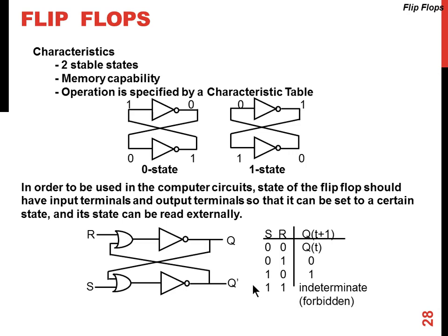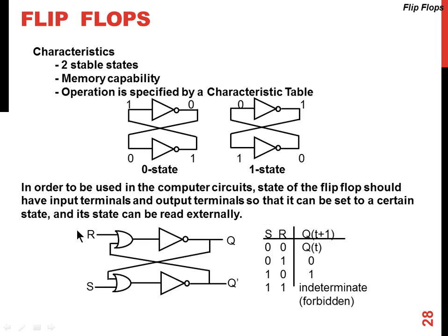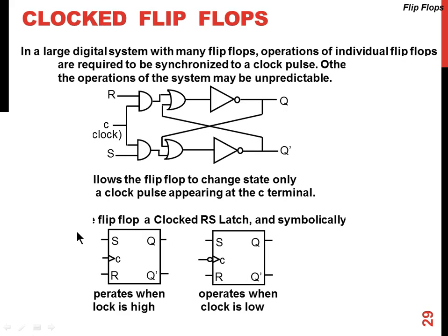So these are normal flip flops, SR flip flops. This is a clocked flip flop, where there is a clock involved for the flip flop. And then we also have basic latches and flip flops. This particular latch has preset and clear. The latches that we work with typically are level sensitive devices, which work at the logic high or low level. Flip flops are typically triggered by clock edges. That's a typical difference when we work with latches and flip flops.